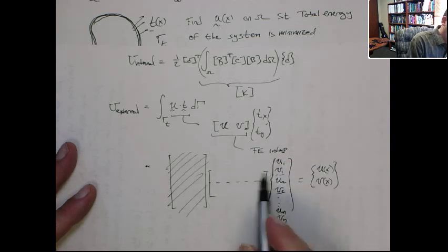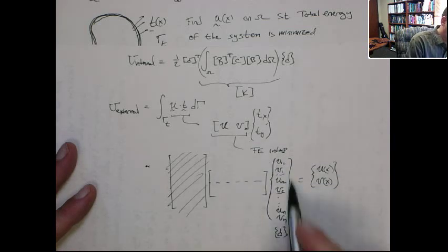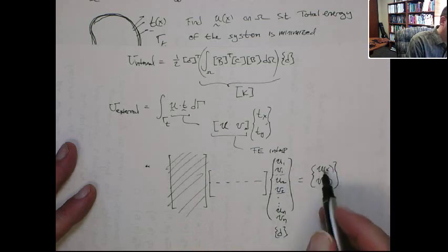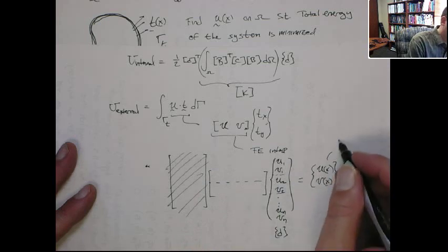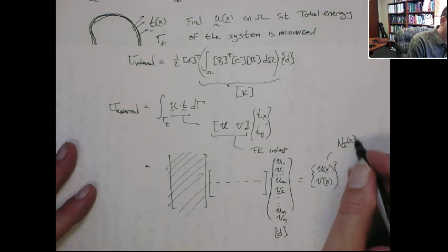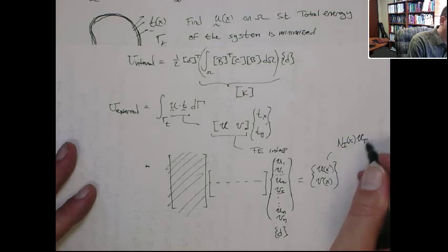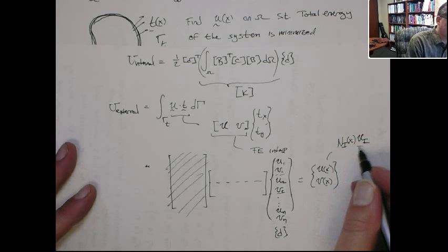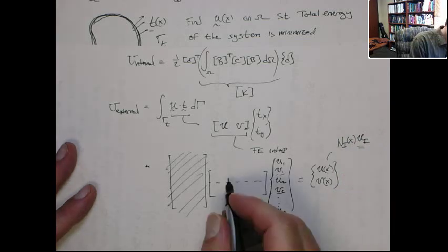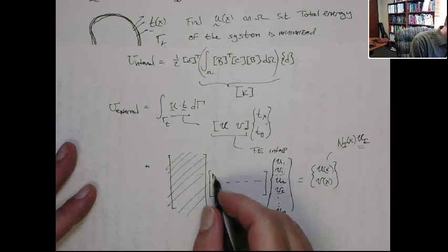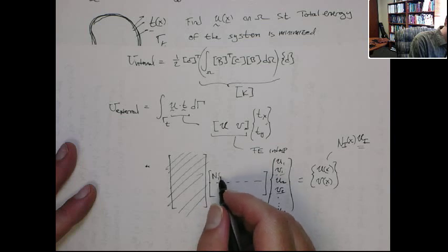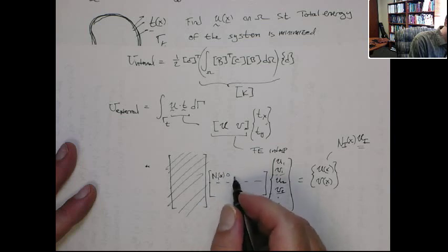Now, this top row gets multiplied by the displacement vector and should give me the u's. Well, we know that this needs to be the Ni's times the nodal unknowns, the x nodal unknowns. It only involves the x degrees of freedom. So everywhere you have the y's, it should be 0. And everywhere you have the x's, you should get the shape function. So it should be something like this.